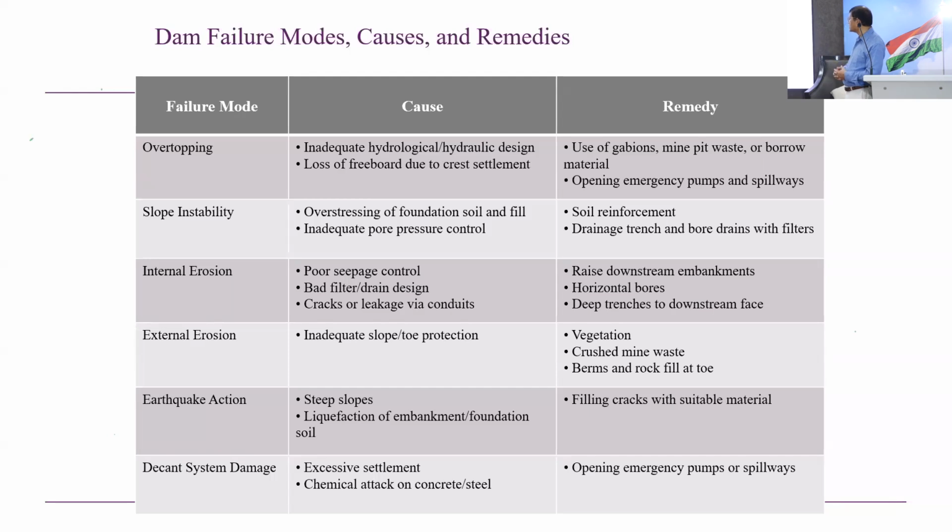And some of the remedies, we use also some gabions or borrow material to stop the overtopping, like increase your height, or we also design some emergency spillways.